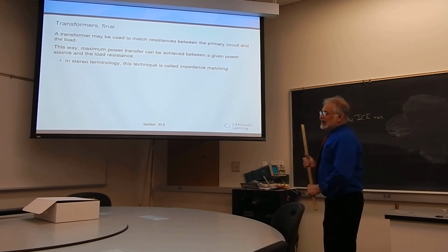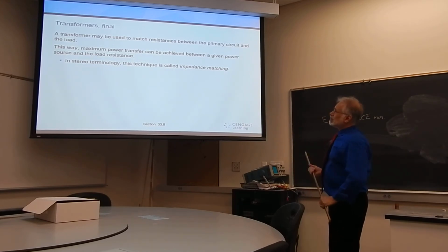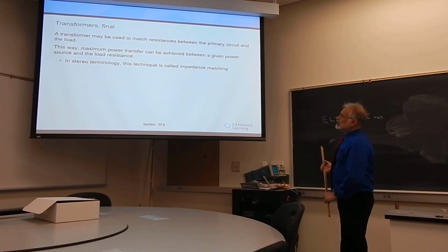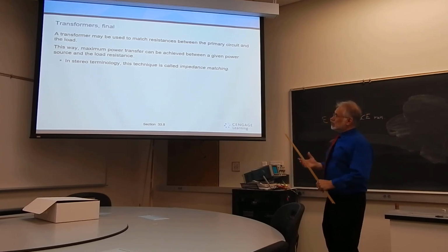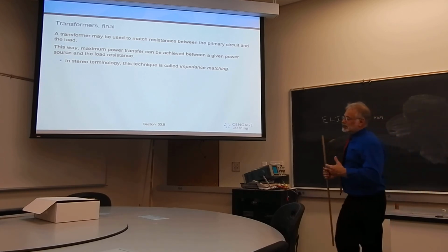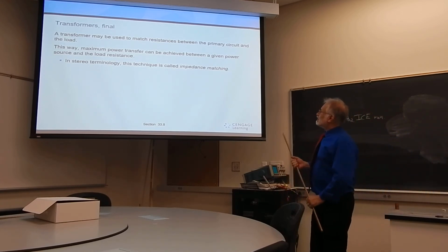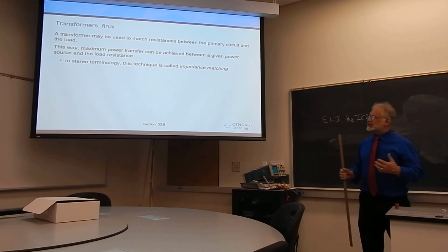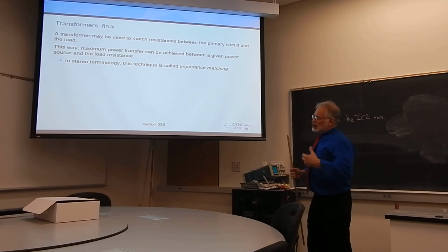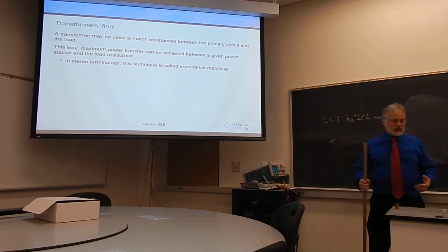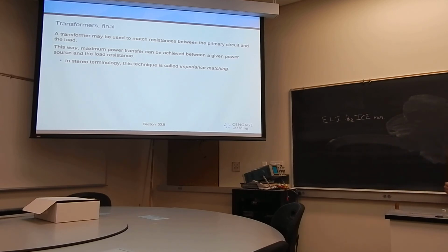Transformers may be used to match resistances between the primary circuit and the load. That way we can ensure maximum power transfer. In stereo applications, this is found between your amplifier and your speakers, a way of impedance matching between your stereo amplifier and your stereo speakers. That's a nice application of that.